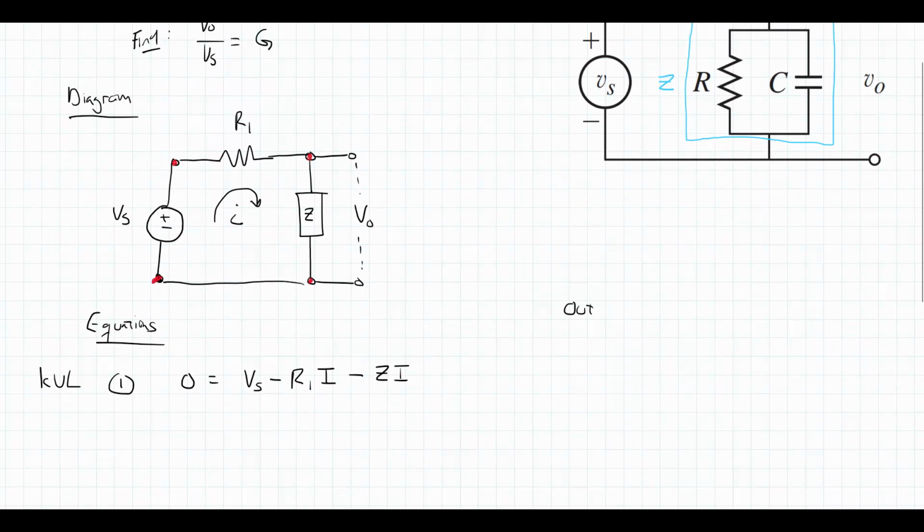So let's track here our outputs and, in this case, just one input. So input, we have Vs, the source voltage, and our output so far is the current I. So nothing yet is complete. We have one equation for one output, but it's not the output that we ultimately want, which is Vout. So we can do here a nodal voltage drop to get a second equation.